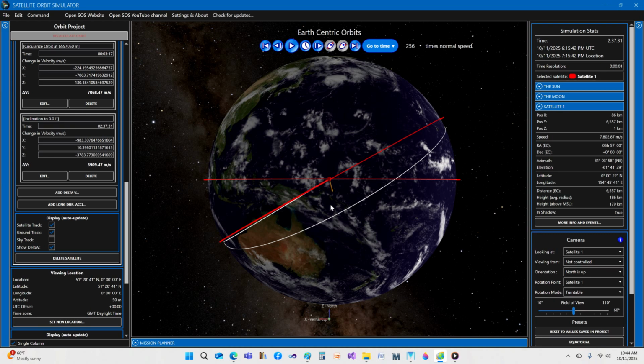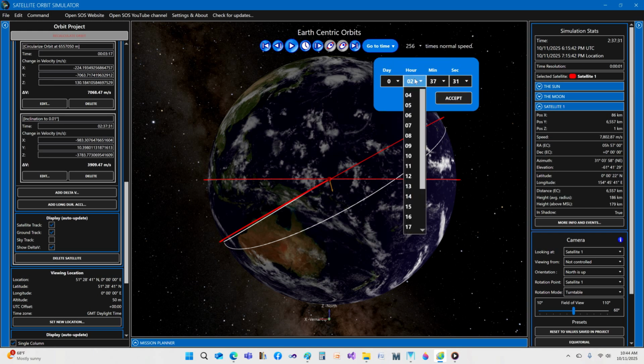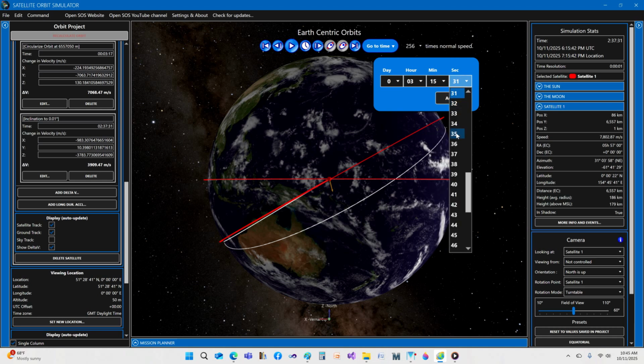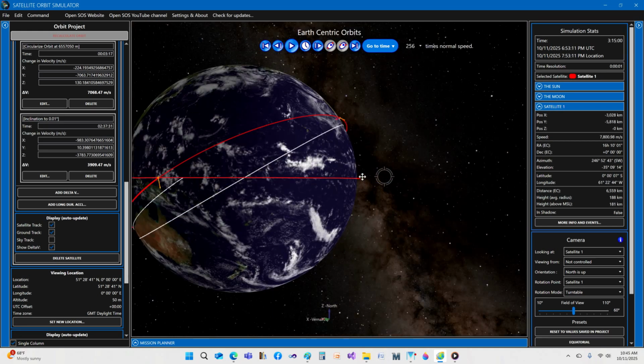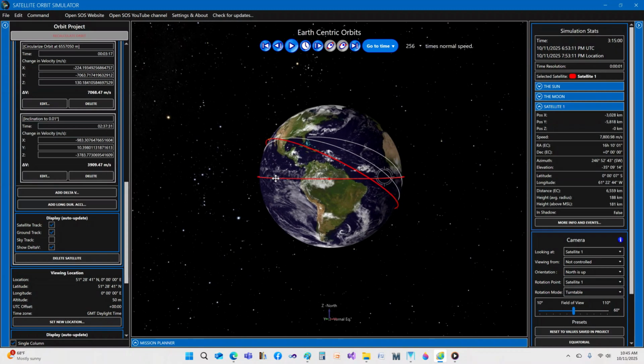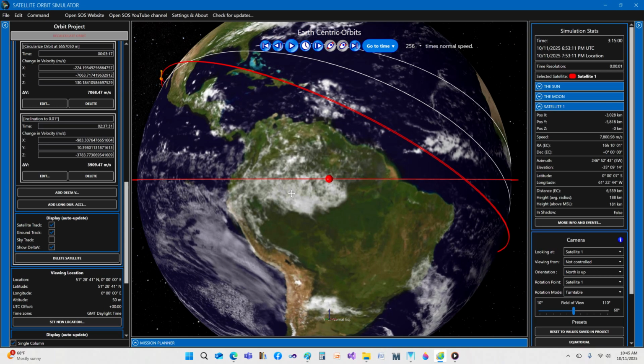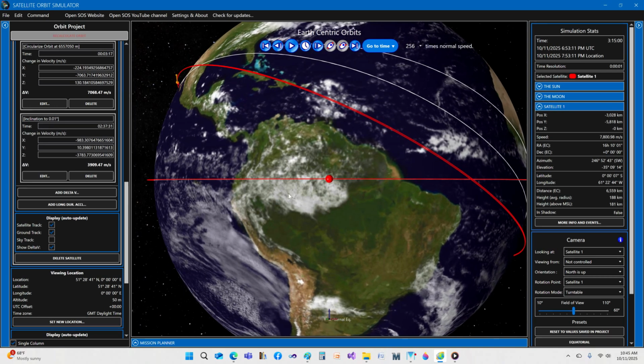appearing stationary above Earth. Now go to simulation time equal to 3 hours and 15 minutes. If the timing for our first burn from low Earth orbit is correct, we can place the satellite over any longitudinal coordinate we want. There is a large ring of these satellites currently in orbit around Earth, serving communications, telecommunications, and weather observation purposes. Next, click on the Add Delta V button.